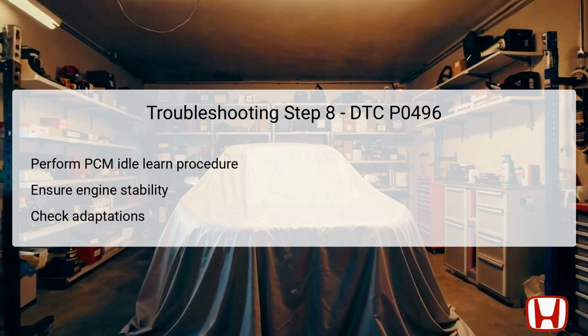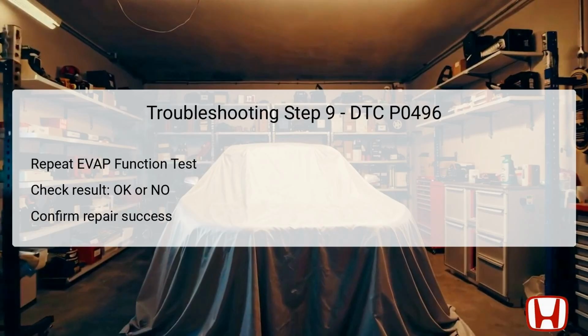Failing to perform this procedure may result in erratic engine behavior, poor performance, or unintended fault codes being triggered. In the final step, repeat the EVAP function test using the Honda Diagnostic System, HDS, to evaluate whether the previous repairs have resolved the P0496 code.